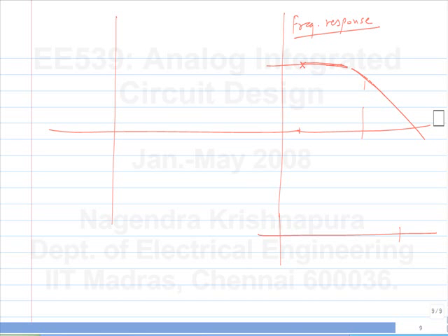Okay. Now let's take a band pass filter for instance. Its transfer function will be something like this. Okay. So that means whatever signal I apply, it tends to first ring at this frequency. Okay. So what I'll do is, I want to extend the bandwidth of this a little bit. So I'll make it ring a little bit at this frequency. Okay. So before it was attenuating, but its own tendency to ring will increase the amplitude at the output at that frequency. Okay. Roughly speaking, that's the explanation for why it enhances the response.